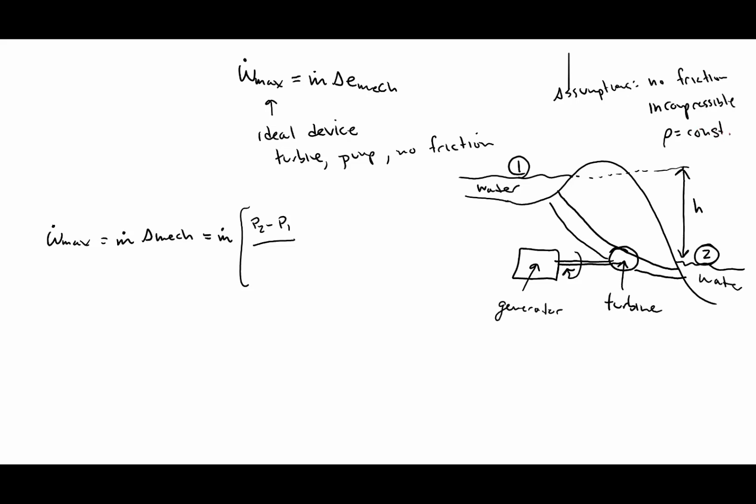And when you're using these equations, you always want to specify what your assumptions are, because if you have something that doesn't apply, for instance, if our density isn't constant, so we don't have incompressible flow, that means that we wouldn't be able to use this specific equation that I'm writing.